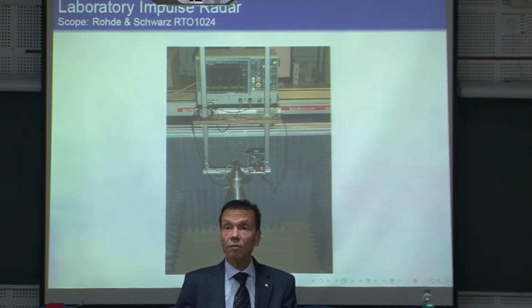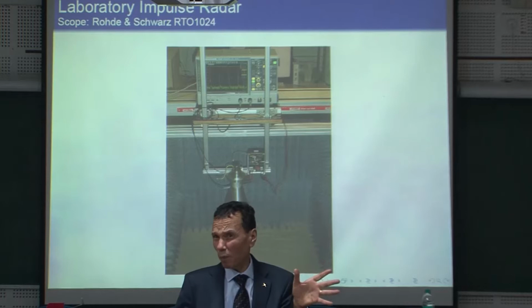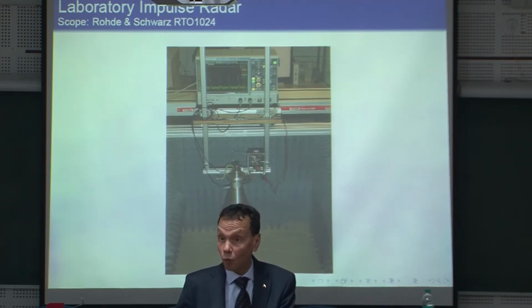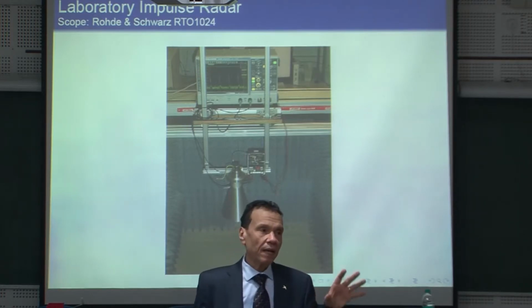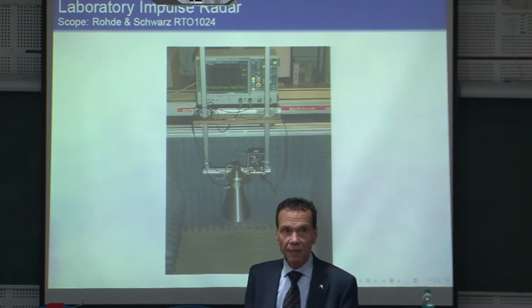If you would like now to penetrate, you should go with the carrier frequency. The fractional bandwidth is a problem, because if you have a fractional bandwidth of 10%, the 10% around 4 giga is only 400 mega, but the 10% around the 40 giga is about 4 giga. So actually, this is here for the penetrability. So to have more penetrability.